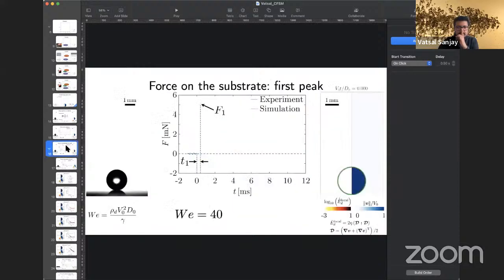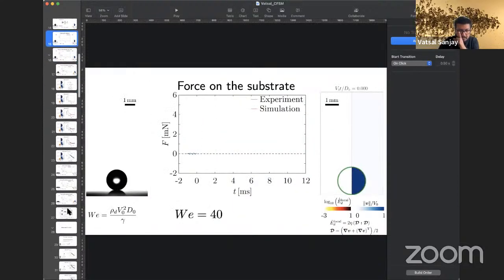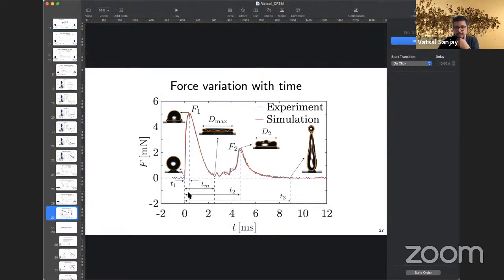So there is a flaw in that assumption, and let me bring out one of the plots here. If you have a spring mass system, the forces there are symmetric. So during the compression stage and the takeoff stage, you would get a symmetric force curve, which we don't see here. In fact, the force peak in both the impact as well as takeoff is quite skewed to one or the other side.